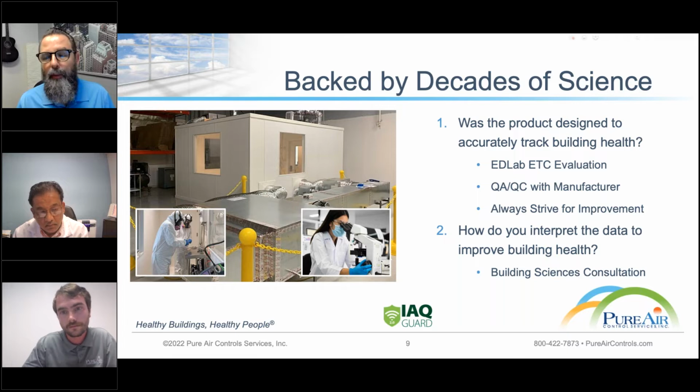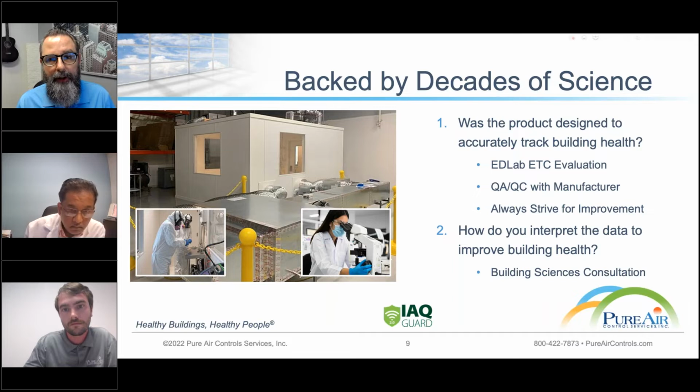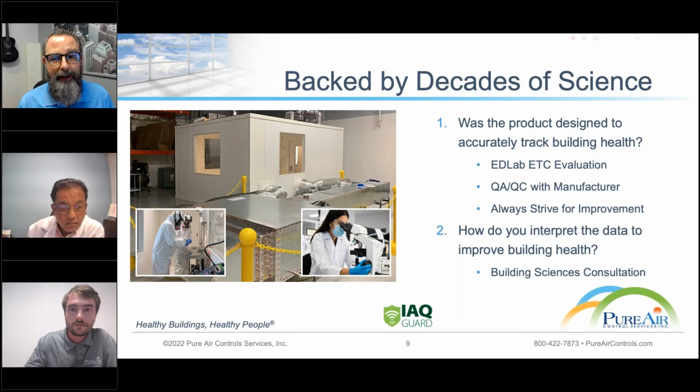Whereas in a world without this type of 24/7 monitoring capability, you would rely on customer, or I should say occupant complaints, right? Within a building, you know something's going on, and then you would have to deploy a large team to come out and investigate the building. Well, now this gives us a head start, like Nick was saying, because we can start to look at the archival data, we can look at what the baseline was, what this negative trend is, and then start to develop a plan to deploy to actually figure out what's going on and remediate it.